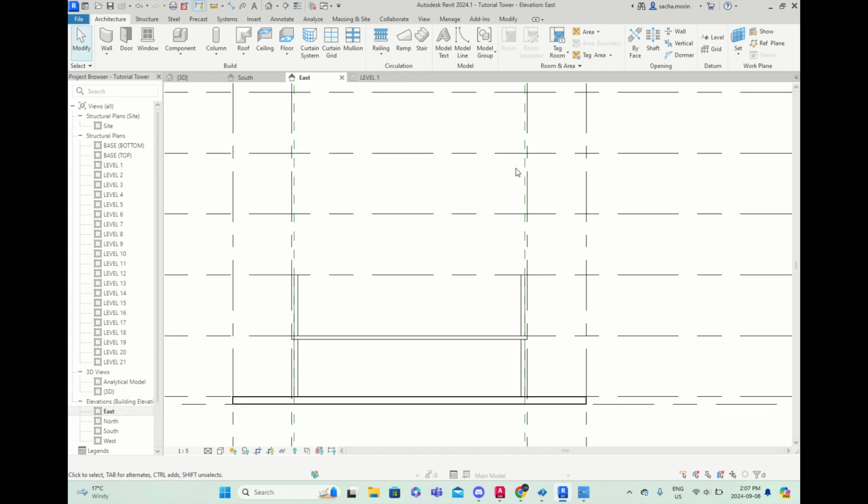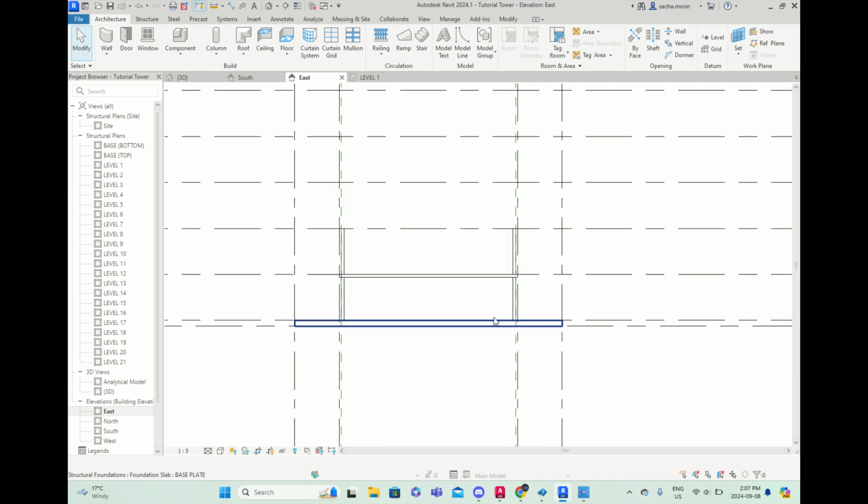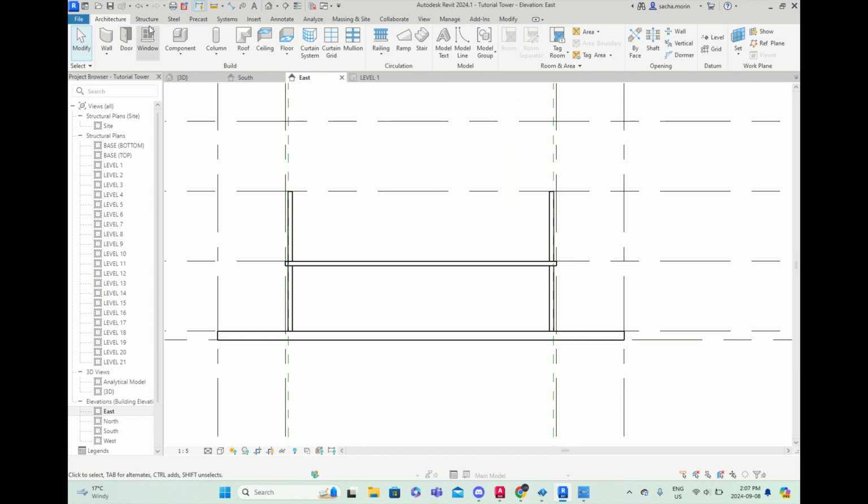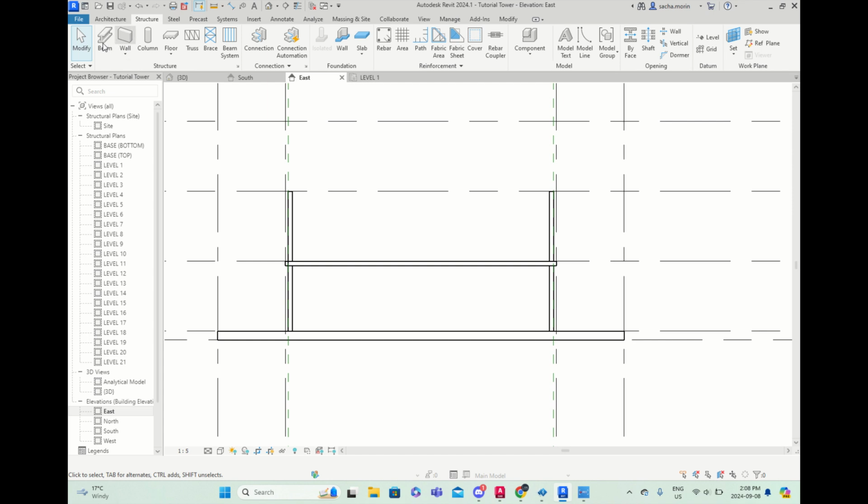Now let's go to our east side view. Before I start using the beam, let's remember what we did when we made the actual horizontal beams. We made a reference plane such that we could trim the excess of our beam, and the same is going to go for the braces, which, by the way, are also built with the beam tool, not the brace tool.